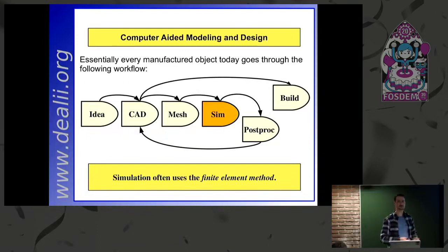There's others, finite differences and finite volumes. The finite elements fundamentally says you have your object that you want to see how it deforms under a force, for example. You break it into virtual very small chunks, and then you write down equations that say, well, each one of these chunks deforms in this particular way in response to the deformations of the neighboring chunks. So these are what we call the elements.